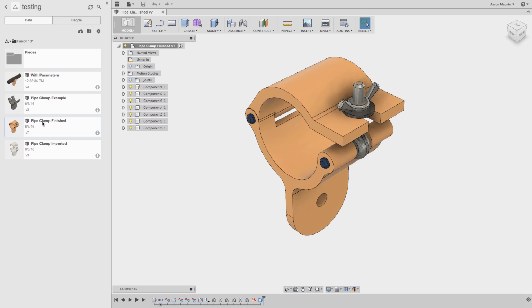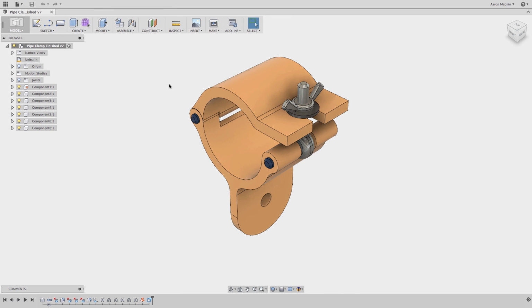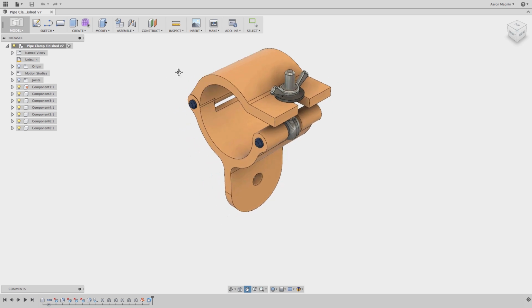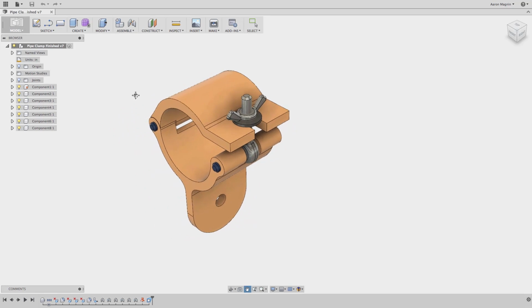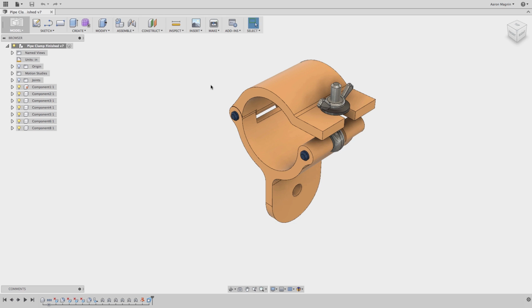So now that I have that open, I don't need to continue seeing my data panel. I can just hit the X up here to close it, and then I can move my mouse cursor right into this workspace that I want to be accessing at this point. So again, let's talk about some of these navigation techniques. If I click and hold the mouse wheel, your icon will change to show you that little hand, and that is going to indicate that you're panning back and forth. So I'm just going to move this back and forth a couple times just to indicate what we're doing there. Once I let go, the mouse cursor changes to indicate you're just back in your normal selection tool.